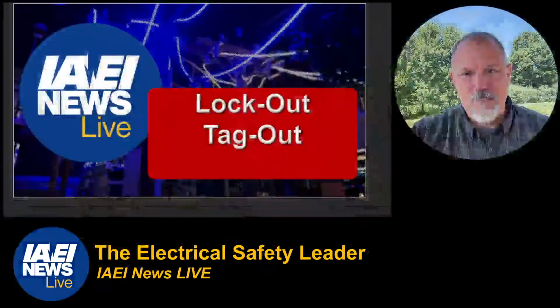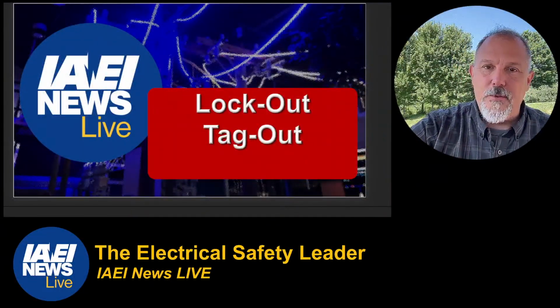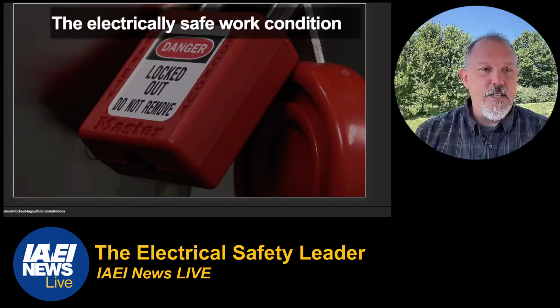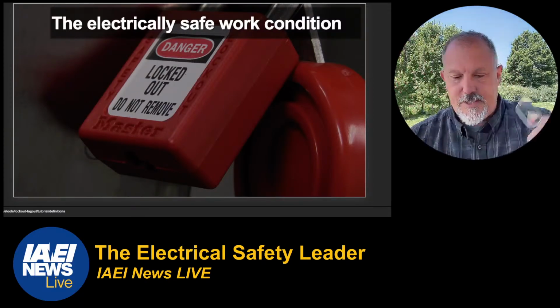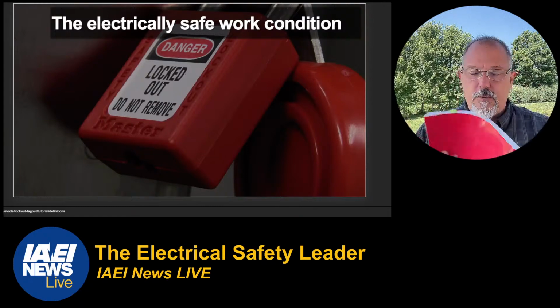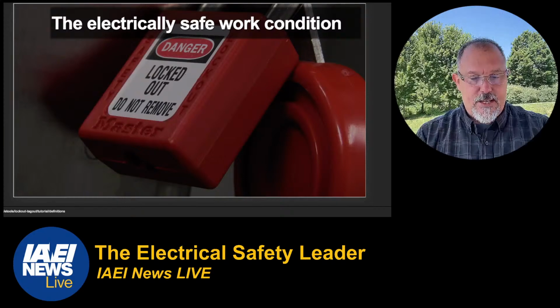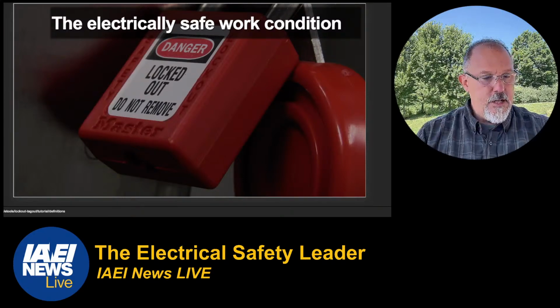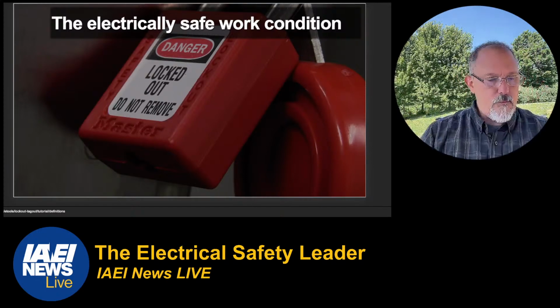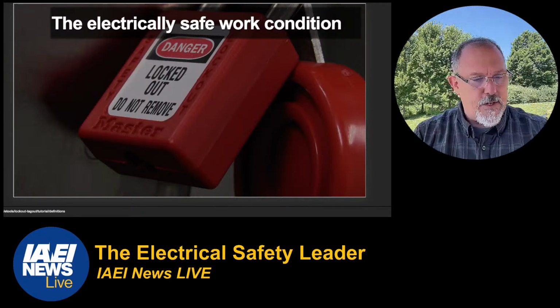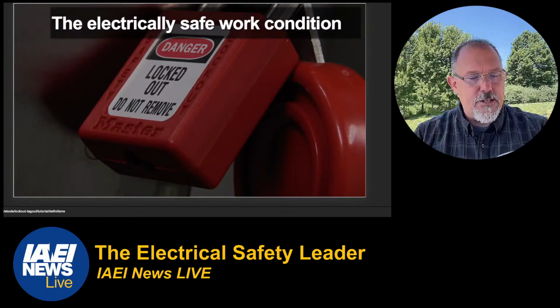So let's take a look and walk down through the concept of lockout tagout. It is a part of establishing an electrically safe work condition. If you look at NFPA 70E, there's a chapter in here, Chapter 1, establishing an electrically safe work condition, which is Article 120. Article 120 is going to be a really good and important reference for us.